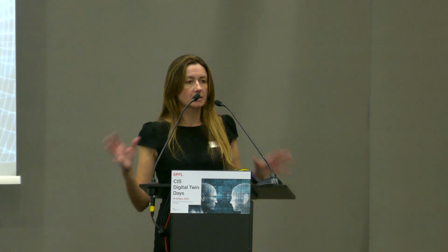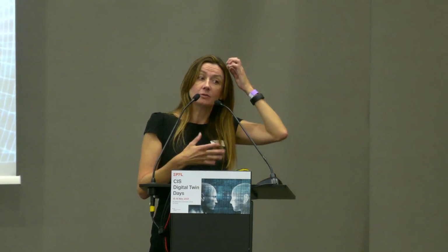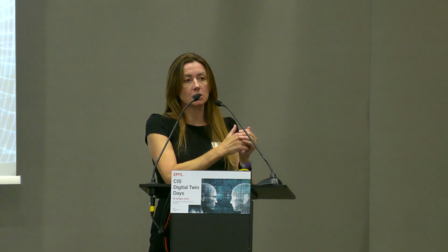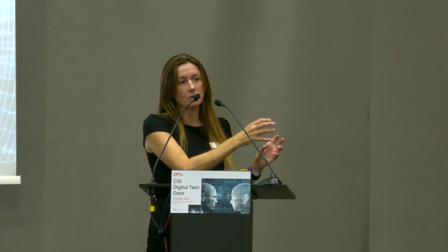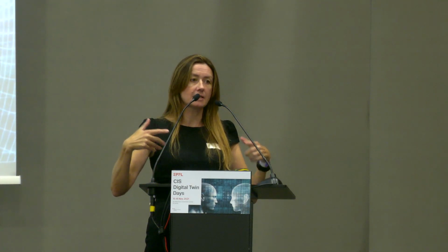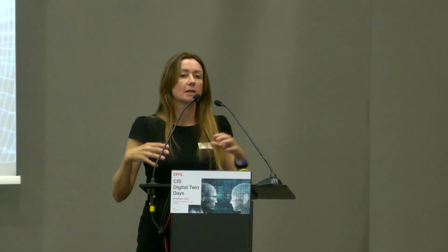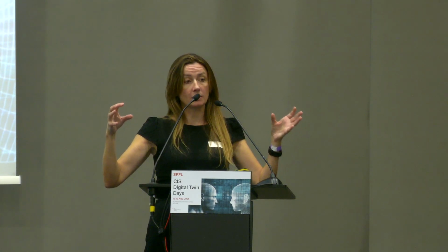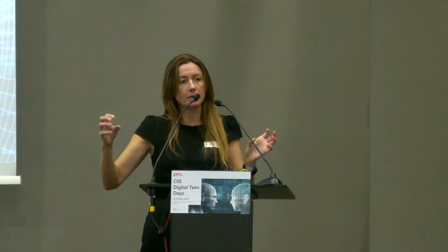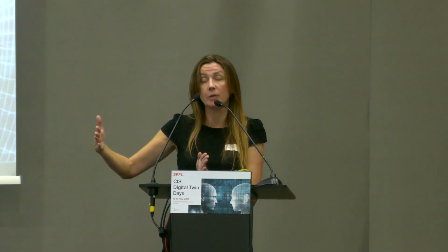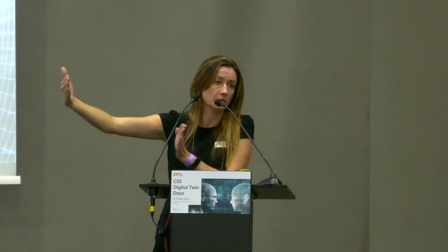Yeah, absolutely. So this is a critical part. In fact, that's the technical part of the talk I took out to try to stay within time. So I'll tell you what we've done, but again, I think this is certainly an area that needs more attention. If you look in the literature, there's been a lot of work done on adaptation of reduced models, and there's a variety of different ways you can do it with, for example, low-rank updates and fast adaptation. The approach that we took, because I mentioned we were working with Axelos on the reduced models, and Axelos builds the reduced models with a component-based approach. So building reduced order models on the components, and then very cleverly putting those together to create the system-level model. For example, our aircraft wing that you saw there had 15 components on the wing.